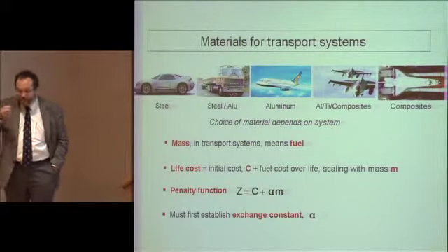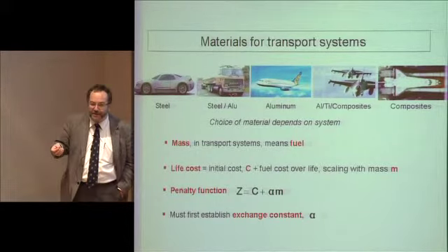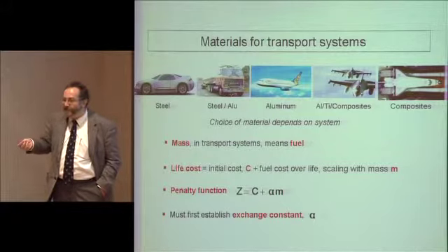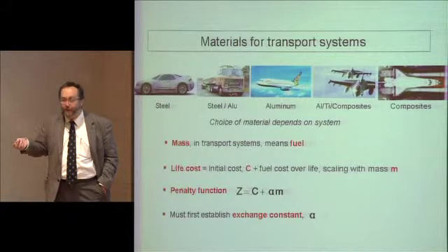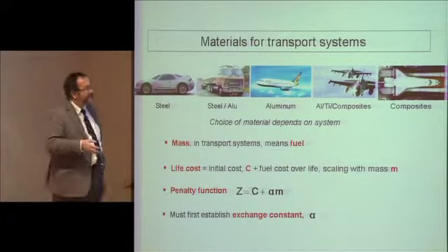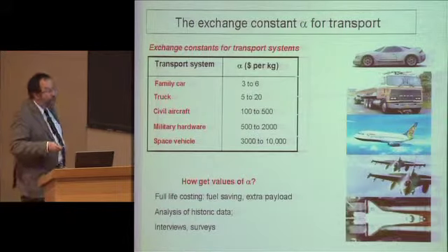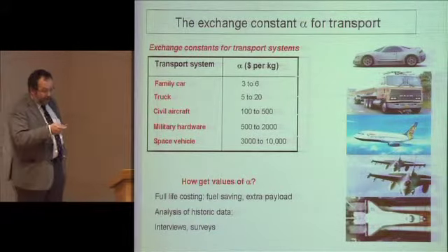and you know that a passenger plus the seat plus 1/10 of the air hostess plus luggage is around 500 kilos, you could say, okay, I'm going to save 1/500th of a passenger when I've saved 1 kilo on the aircraft, and you need to see how much you're prepared to pay for that. So with this value analysis, you can have estimates of the various costs per kilo.